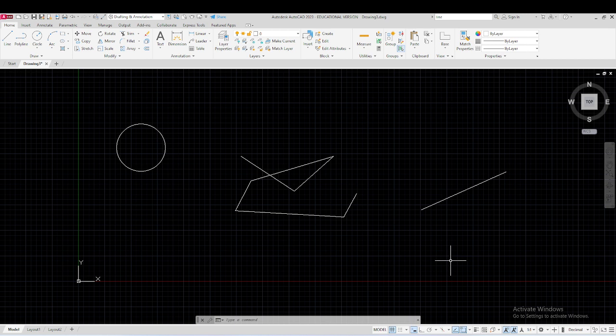So we can use our cursor or the tooltip of this tool to get into any command or to access any tool or command. For example, if I have to enter the line command, instead of going here and typing a command, or instead of going here and selecting that command, I can just type that command in the normal mode of the cursor.